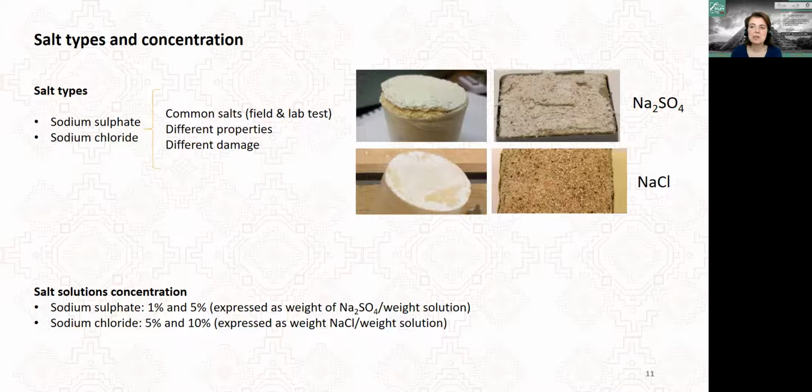Regarding salt solution concentration, this was one of the most complex points to be solved in defining the procedure. We had to decide first of all if we wanted to have a constant amount of salt expressed as percentage of the dry weight, or if we wanted to use a constant salt solution concentration. Finally, after testing and discussing, we decided to use a constant salt solution concentration because in this way we are more closely reproducing the situation in the field in which a substrate will absorb the same type of solution.